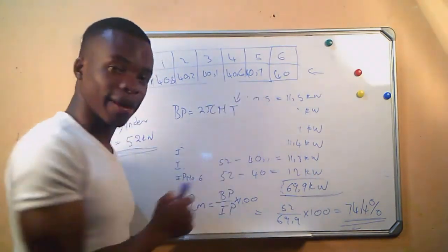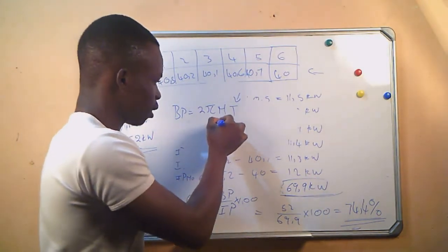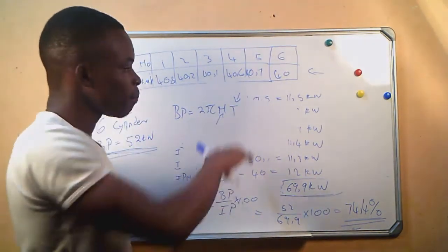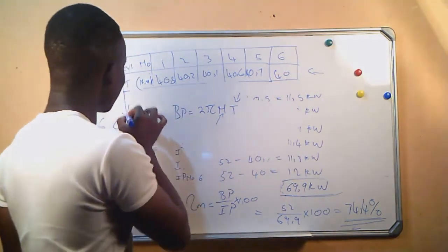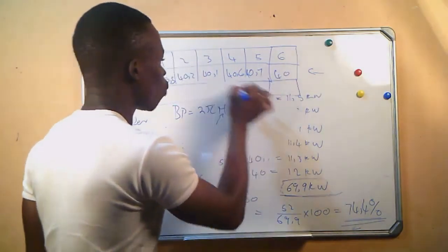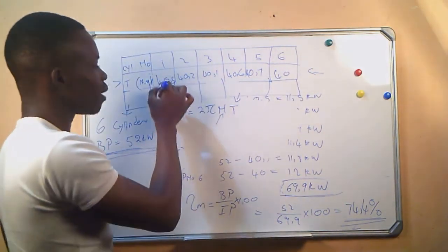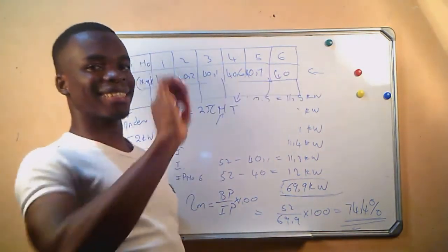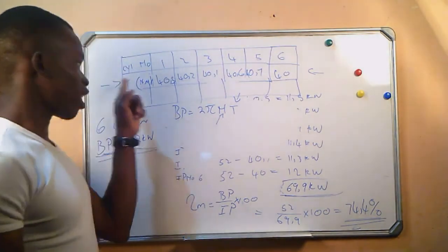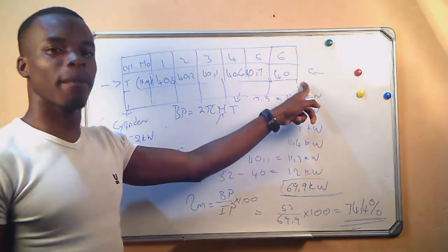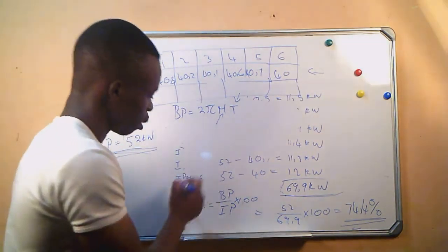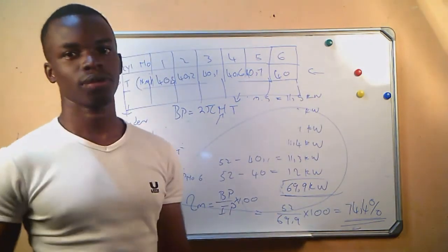Put the torque here. The rotational frequency will be given. After, you are able to create another column where you record the brake power for each cylinder. If you are given the torque, you must first calculate the brake power yourself, and then you come to this stage.